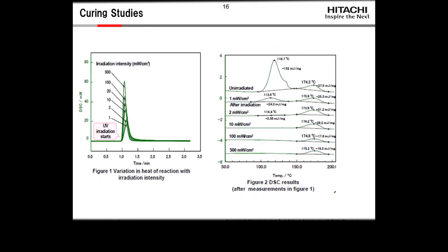If we look at materials that cure in the DSC, whether we cure by light or whether we cure by heat, it turns out to give us very similar data. If we look at radiation curing, because a lot of people are moving to optical curing methods where we irradiate because you get fewer VOCs, so you have less pollution, we can see that as intensity increases, the energy of the cure increases.